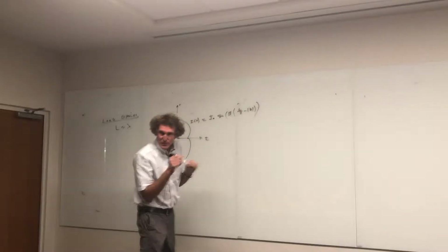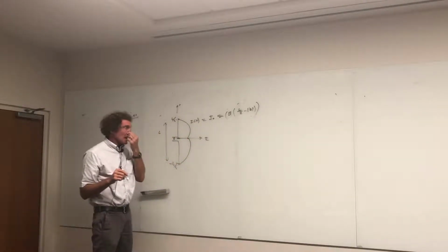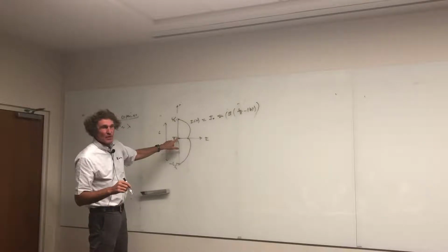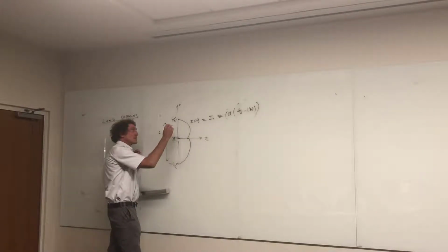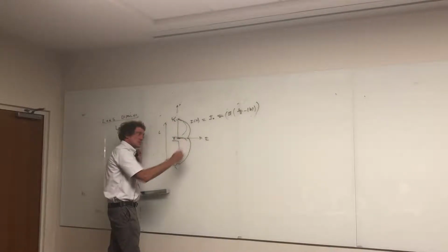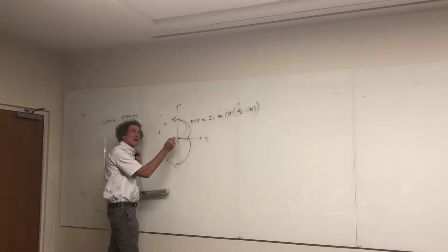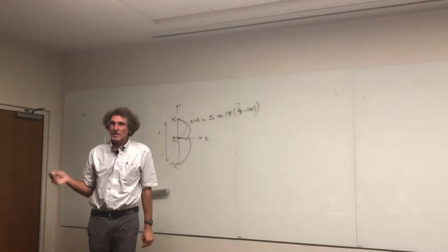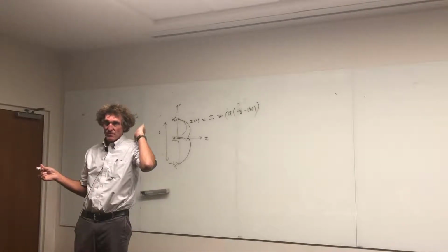Sine of pi over 2, 90 degrees, is 0. It means it would go to 0 here. Now, if it was a wavelength long, you would have this kind of current distribution, all right? You're feeding right here, you literally have no current going in. It means the impedance of that antenna is about infinite, just so you know. You follow me on this?